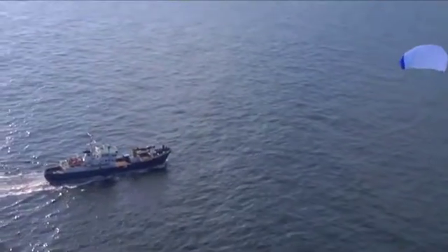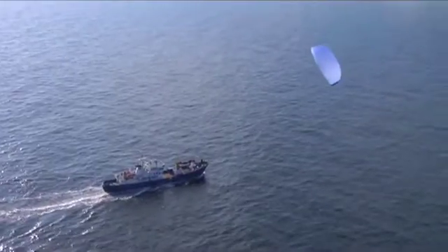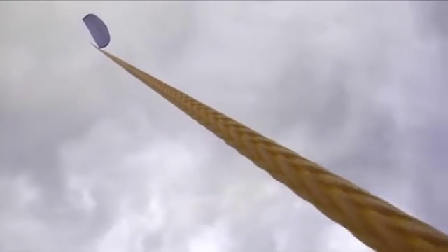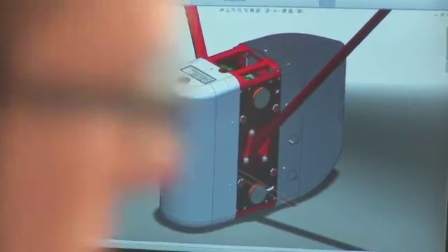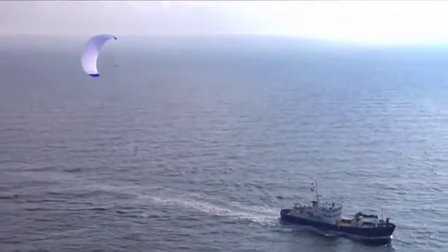It's possible to have a high speed, and if we double the speed, we have 4 times the pulling force on the ship. And so all these forces are coming from the kite through the control pod and from there further into the towing rope. It's very important to check the clearances, and we're using SolidWorks for that, so we have this clearance, but we also have minimum space so that afterwards the whole structure is as small as possible.